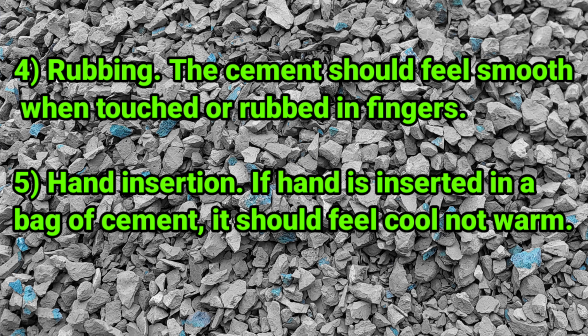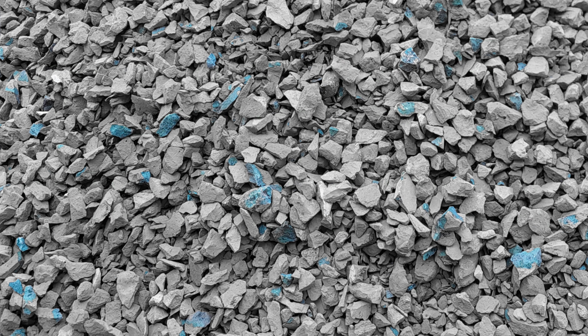Number 4, rubbing. The cement should feel smooth when touched or rubbed in fingers. Number 5, hand insertion. If a hand is inserted in a bag of cement, it should feel cool, not warm.